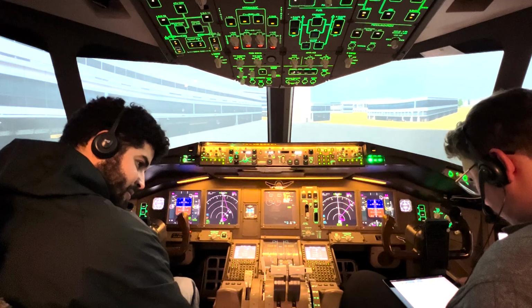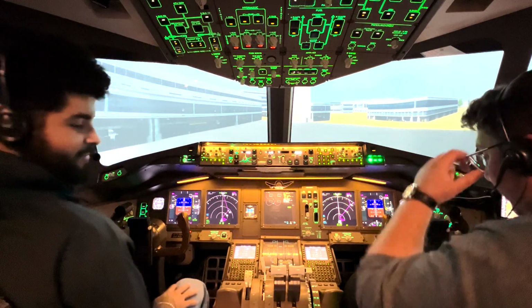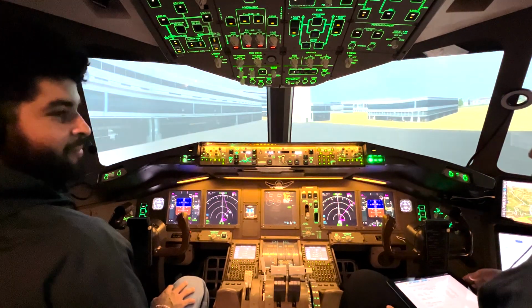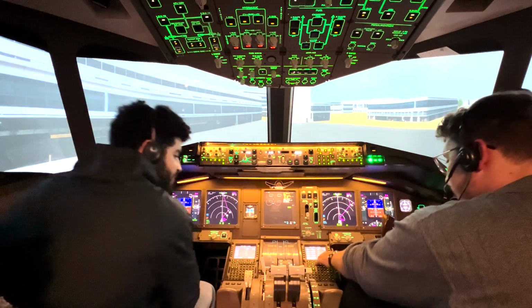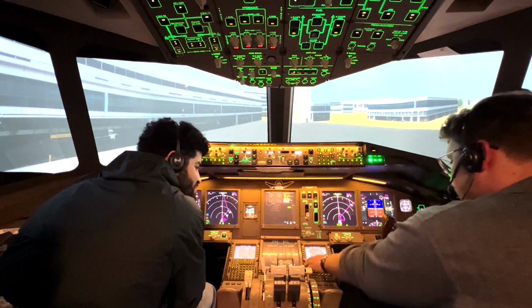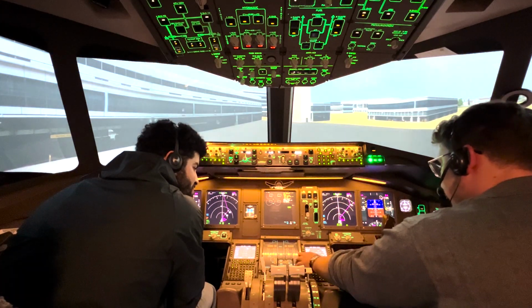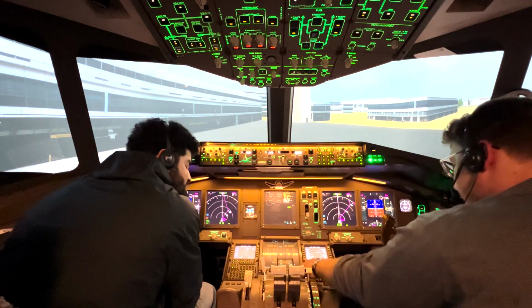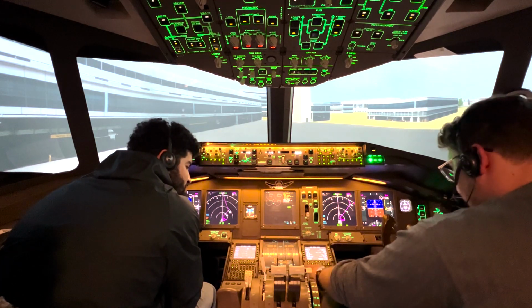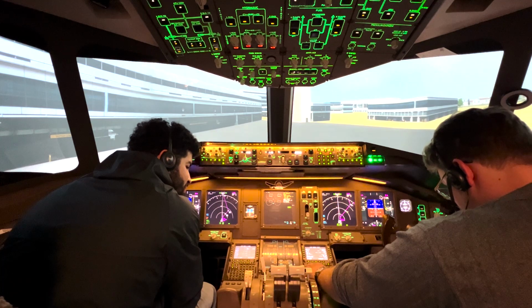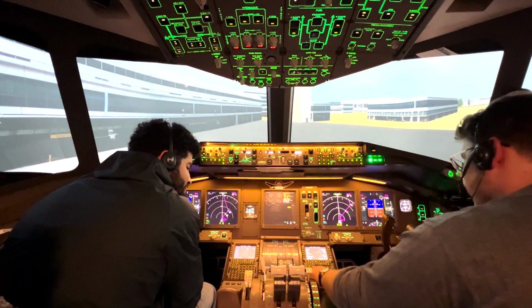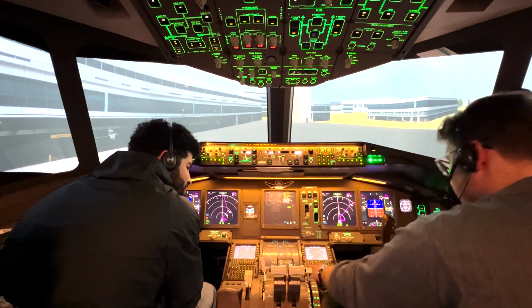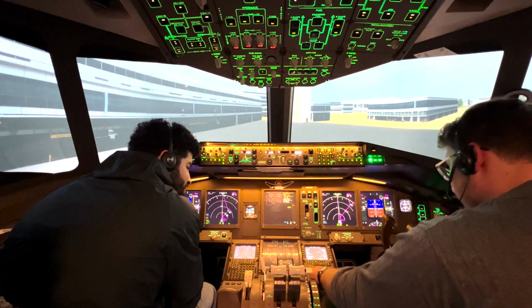Now we're going to program our performance so that we can have a good optimized takeoff, and we know what our speed is that we need to pull back. So we'll go ahead and go back into route performance initialization. We'll load our zero fuel weight from our program, and our reserve is going to be 2. Cruising altitude for today's flight is flight level 380, so we're flying at 38,000 feet. Our cost index is 149.